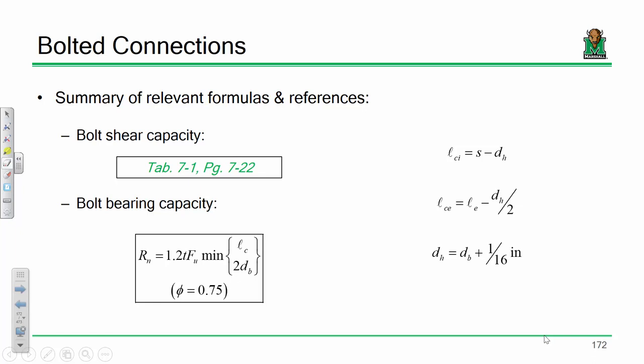Alright, is that enough? Okay, so we've been talking about bolted connections in here for a while before the exam, so I felt it prudent to go back to square one with bolted connection analysis. Remember that primarily the two types of bolted connections that we as structural engineers have to assess are bearing type connections and then slip critical connections. We will probably get to discussing slip critical connections today.